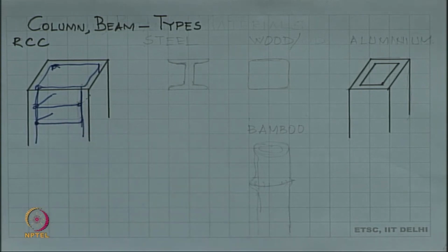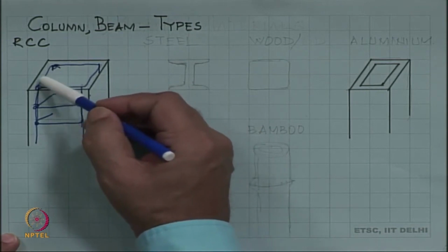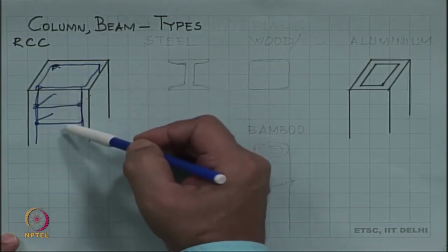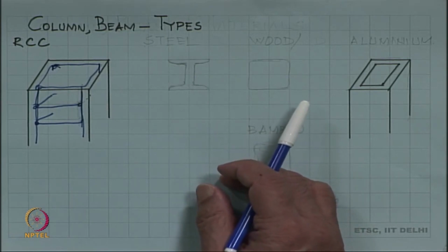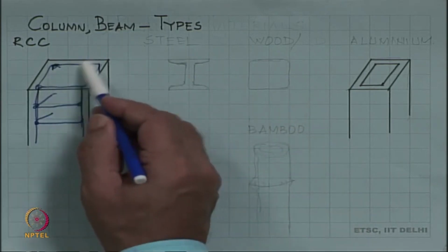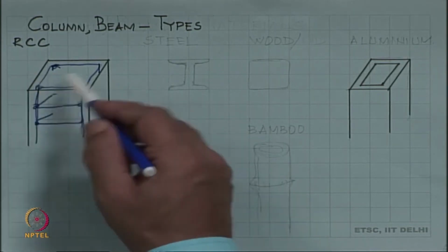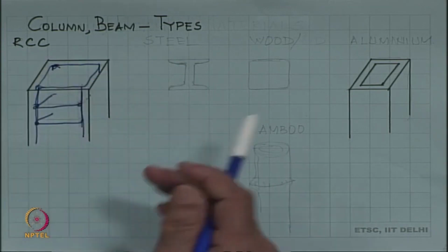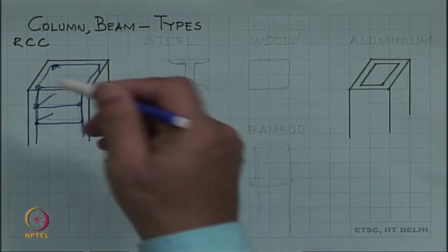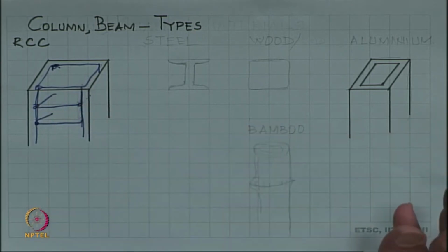So, you have created a series of long wires. There could be this, or there could be even more in between. Some would be thick in diameter, some could be thin, depending on what load has to be taken, and then they are all tied up together. After this is tied, it is put in place, and around it we have a box like structure in which the concrete is poured, it sets, and then its outside is removed, and we have our column.